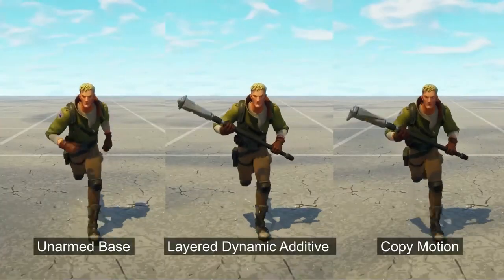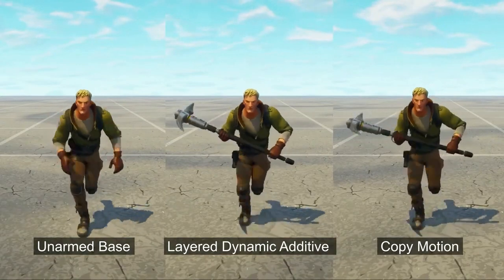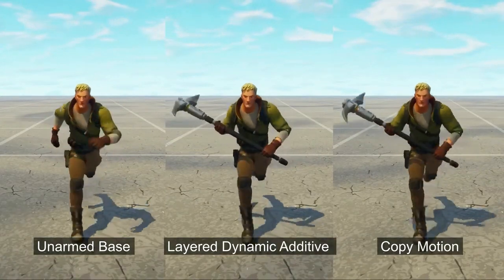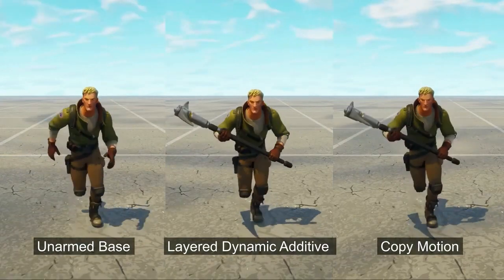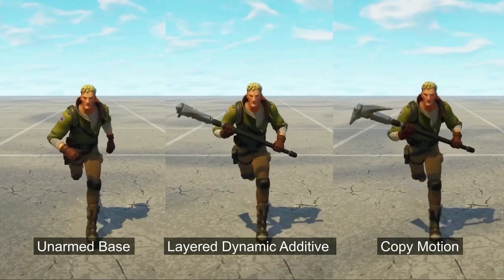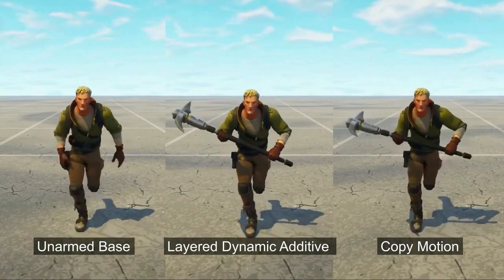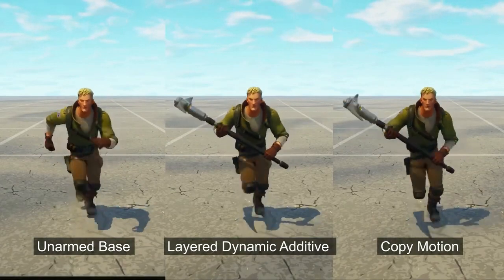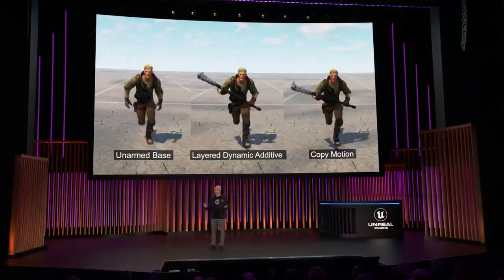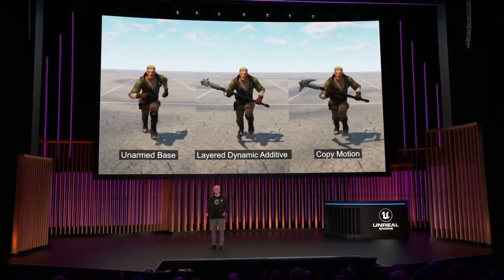As you can see on the middle clip, the additive on its own was good enough for the body, but the arms looked very stiff. It was impossible to use the hand motions as is, because they're in the wrong direction. Using Copy Motion and pose history, we could reorient and delay the curves by just a few frames. This allows us to make heavy items feel weighty entirely at runtime. Finally, we apply this motion curve to our hand IK effectors and elbow controls.